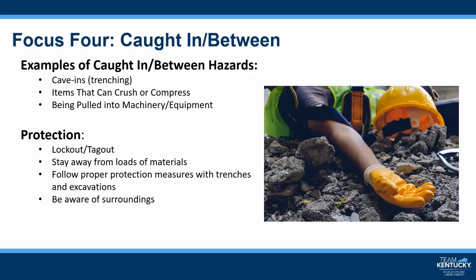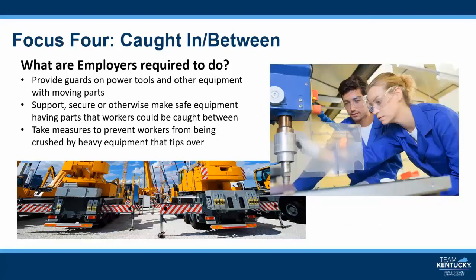When workers are working in or even around a trench or an excavation, the proper safety measures should be taken to prevent a cave-in. Employers are required to provide guards on power tools and other equipment with moving parts. Employers are also required to support, secure, or otherwise make equipment safe that has parts that workers could be caught between. They are also required to take measures to prevent workers from being crushed by heavy equipment that tips over.